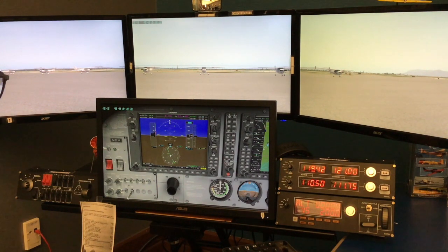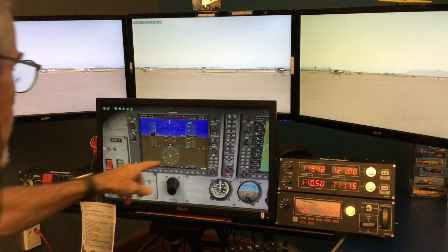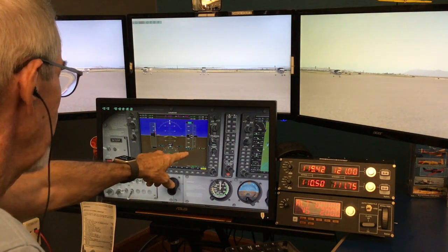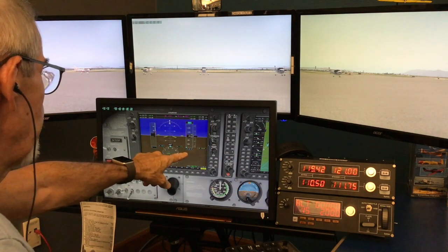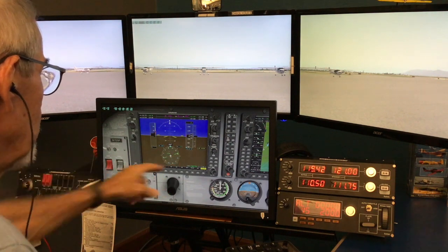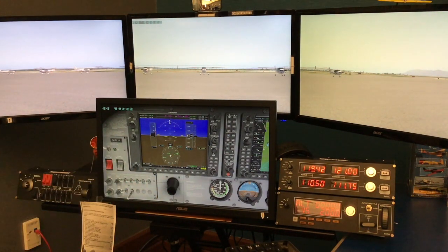Oh, there's a slight difference, that's the barometric. I'm sorry, I was a little off on that. That's the barometric. The center one is the course. There we go. So now once I get my needle on there, you can set that the way you want. The outer one sets the barometric pressure, which is down here. So if you were saying 29.92, standard barometric pressure, it would be like so. And if it was a standard day at Glendale, we would have the Glendale altitude here.